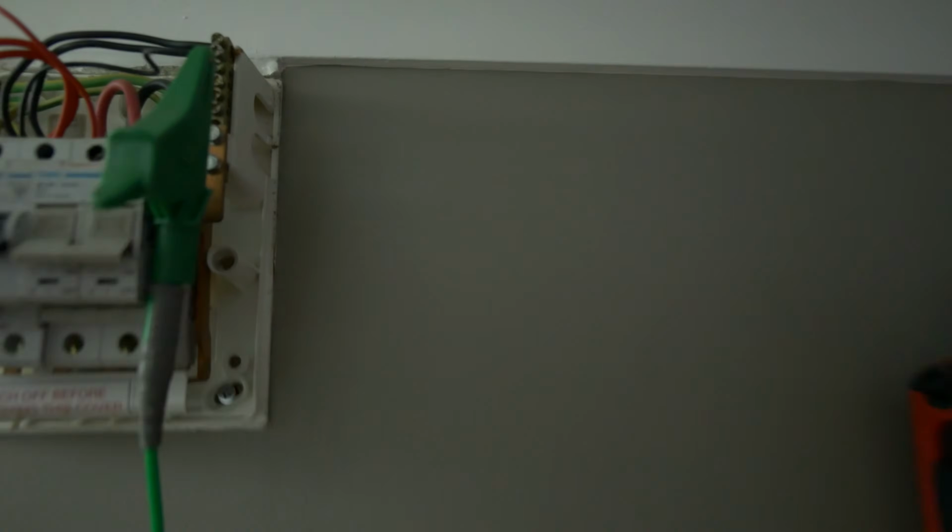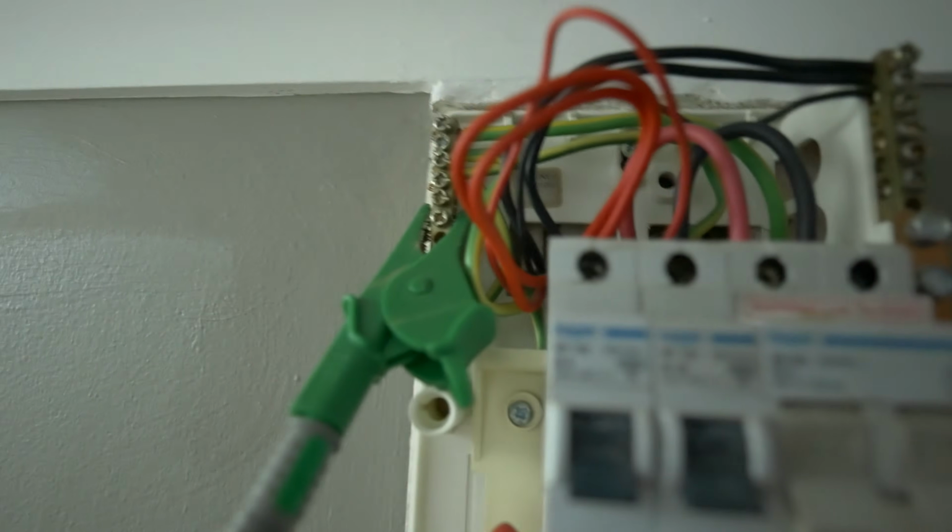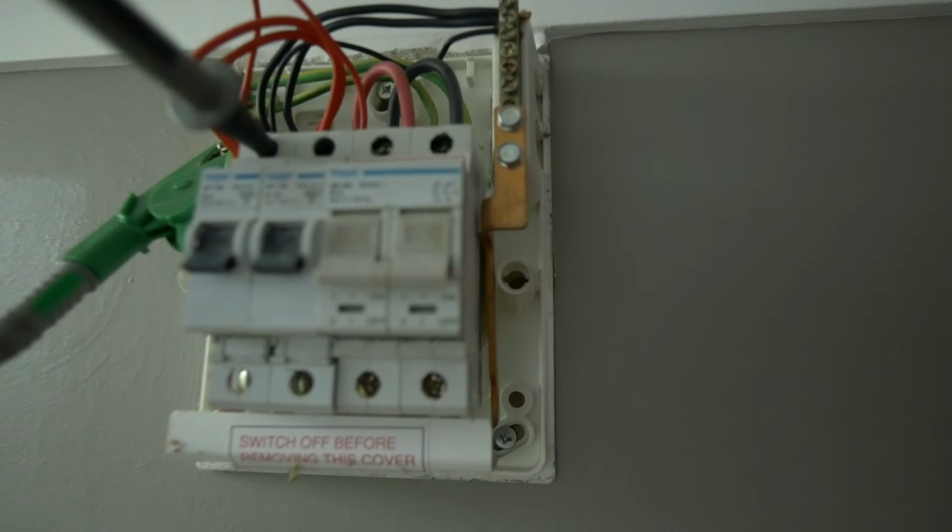And just to prove a point of concept, I'll pop this neutral back into the neutral bar and we'll measure the socket circuit again, and I'll show you what I meant at the start of all this. Seeing is sometimes believing. So same test, we're on the earth bar there. If I probe onto the line connection for this socket circuit, all I've done is pop the light in neutral back into the neutral bar. If I hit test, in theory I'd expect to see this come out at around 20 megaohm as well, which it is doing, if that'll focus.